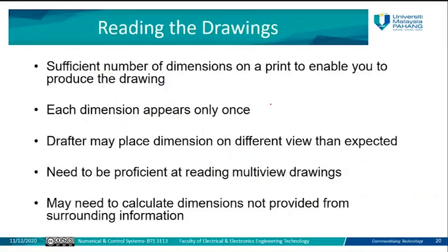So how do we actually read these drawings? As a CNC programmer, for example, you want to write a program for the machine. You have the drawings, but how do you convert a drawing into a real program? First, you need to know what happens when I ask the machine to go right, go left, go up, go down, or make the table move left or right. All of this is based on coordinates, which means it is also based on dimensions.